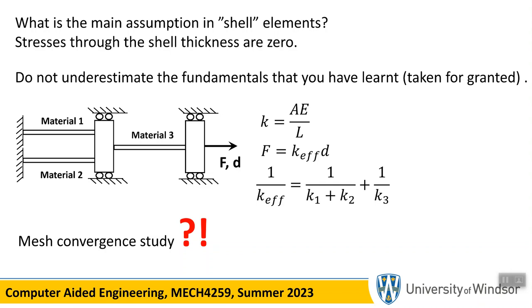And the idea is to take a finer mesh, but a finer mesh in critical areas. Don't take a fine mesh in an area which is inconsequential. So you have to have developed some kind of a feeling for where the critical areas are. Get the results for that particular mesh, then refine the mesh in that area and compare the results in that same area with what you got before. If there is a significant difference between the two, you might as well forget about the first one and start refining the second mesh. You do this until things don't change that much.